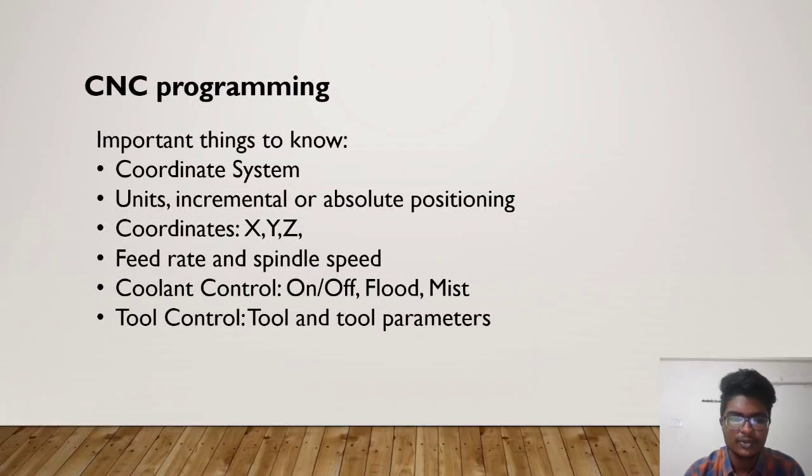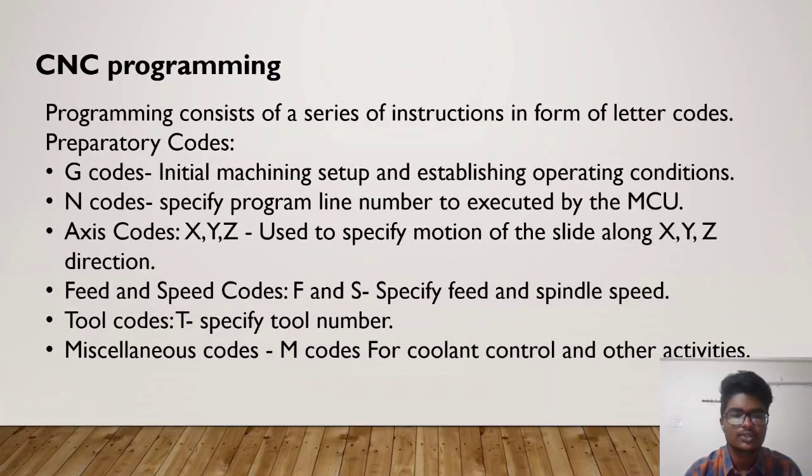So CNC programming: before giving the CNC program, you should know the coordinate system for your workpiece, units, and incremental or absolute positioning, also the coordinates, feed rate and spindle speed, coolant on or off, and tool control for the particular machining of the specific job you need. Programming consists of a series of instructions in the form of letter codes. Let's start with the letter address and its numerical value.